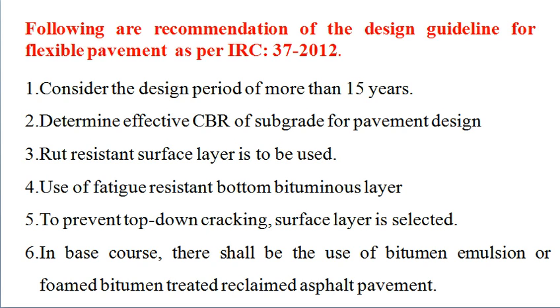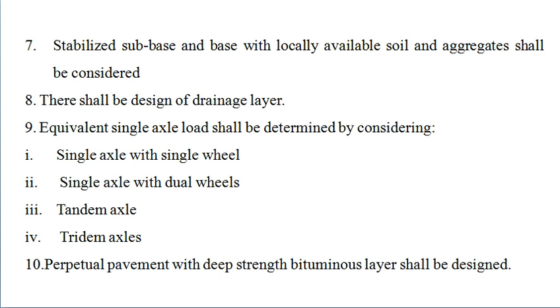Next, in the base course, there shall be the use of bitumen emulsion or foamed bitumen treated reclaimed asphalt pavements. Now, as discussed earlier, there should be an introduction of bitumen into the below lying layers in order to enhance the strength capabilities and the fatigue resistivity of these layers. Next, the stabilized sub-base and base with locally available soil and aggregates shall be considered. This use of locally available soil and aggregates